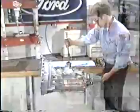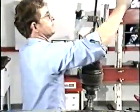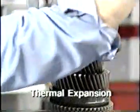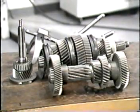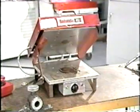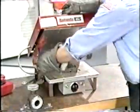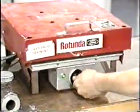Now let's take a look at the S542ZF transmission. It's assembled much differently from the other transmissions we've seen so far. Thermal expansion is required on the ZF because many of its components are attached to the shaft using a shrink fit. A gear heater is the best device to use because you can heat the components evenly. When heating gears, be careful not to exceed the recommended heating times and temperatures listed in the manual.